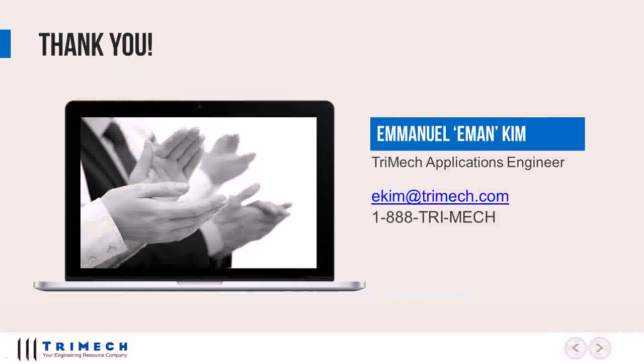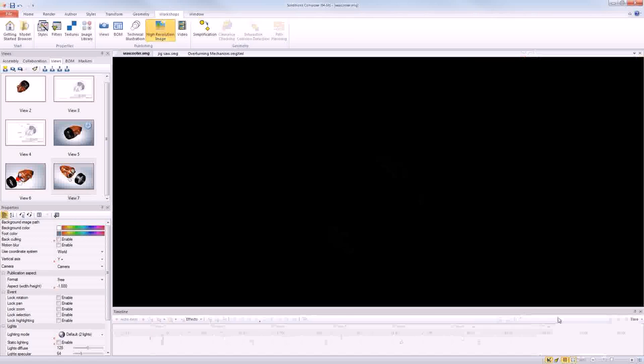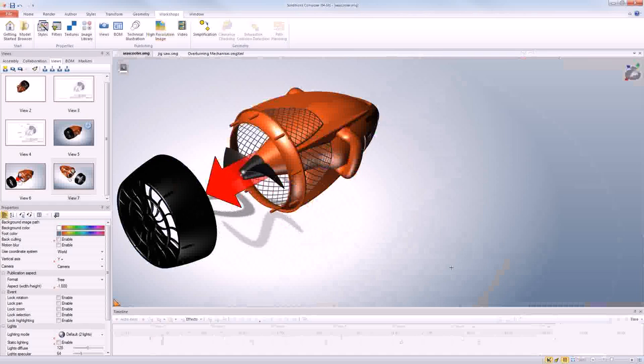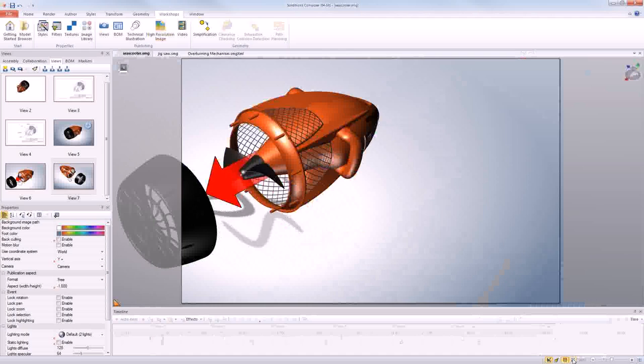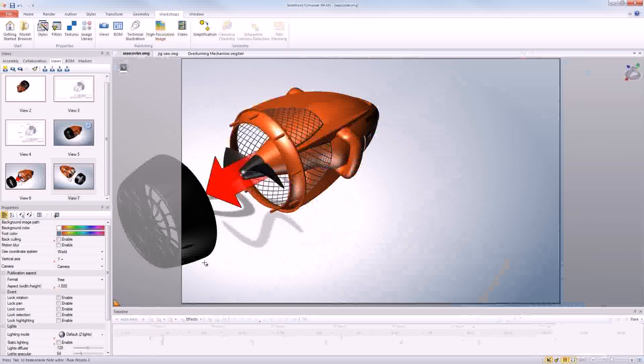Okay, for those of you who are just wondering what is being talked about here, if I turn off the paper space button over here, how do I know if I move this over here like this that it's going to print everything? You really don't know. That's why, before you output, it is a good idea to check your paper space outline to make sure that your entire model is within the printable area. Okay, so great questions.